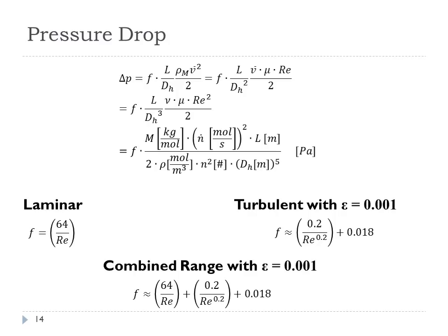When you are between 2,000 and 5,000 Reynolds numbers, you need to use some kind of approximation, and you can roughly approximate that the friction factor looks like a combination from the laminar and turbulent regimes. And so that combined equation is roughly valid over the entire span. Of course, when you know you're in the laminar, you should be using just the laminar equation.